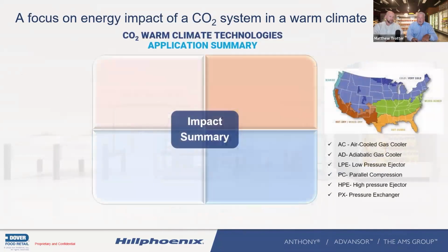So when we really look at what this means to me, how do I understand the best way to use the right technology or the right application for CO2 in a warmer climate? Part of that is, if you're in a cool climate with a low load, you can do air cooled, adiabatic, low pressure ejectors. Remember that each application will vary based on your ambient condition, the size of your system, and what makes sense for your energy rate, your efficiency rate, and how you look at ROI.